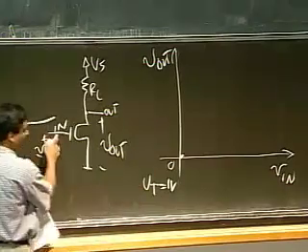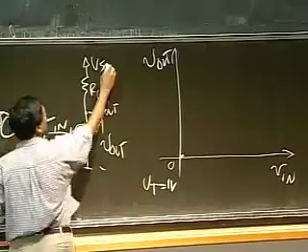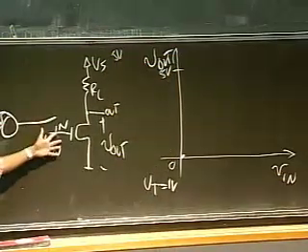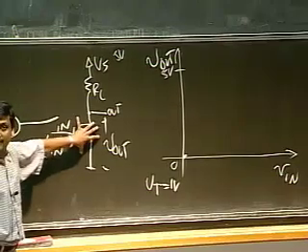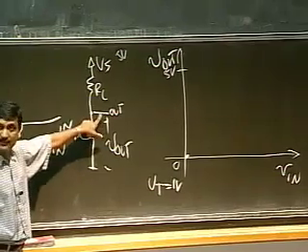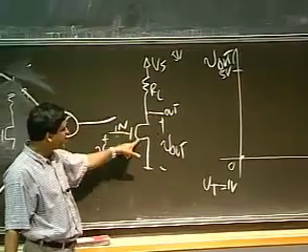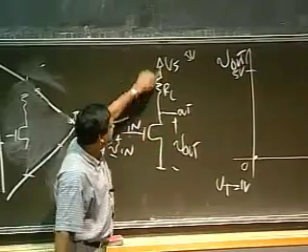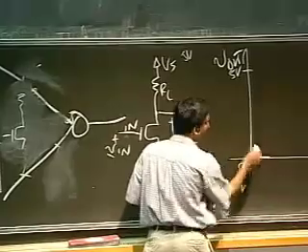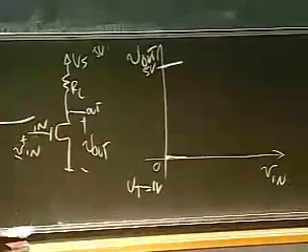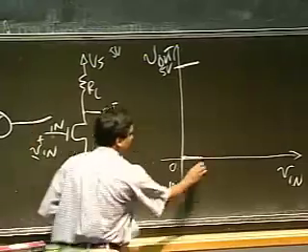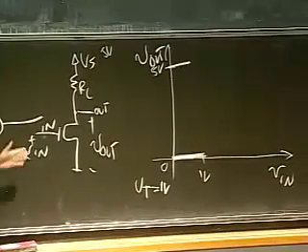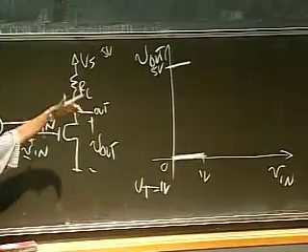So when the input is a 0, and let's say Vs is 5 volts, this guy is turned off. Okay, so what's the output voltage? If this is turned off, what's the output voltage? It's the supply. The supply directly shows up here, and so as long as the input is 0, the output is at 5 volts. And this is true until the input reaches 1 volt. As long as the input is less than 1 volt, my output stays high.